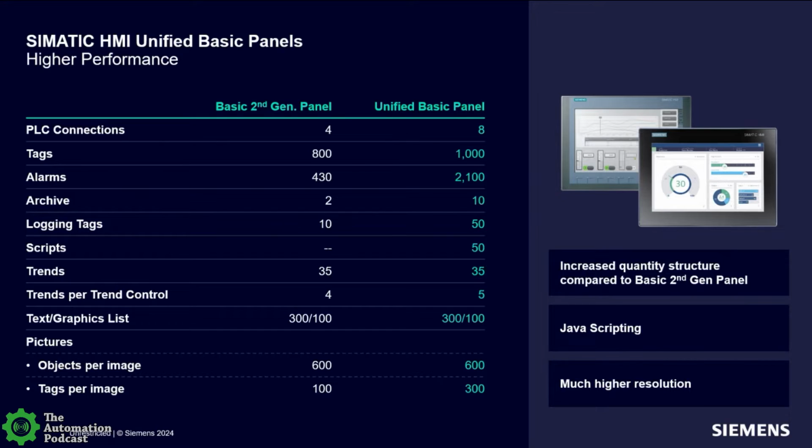But if you start to duplicate that heavily in your project, we like to say use a faceplate, which is a component where you can make that collection of objects together, and then you call that instance of the faceplate as many times as you need, and you're just mapping the new tag information to these faceplate instances. The power of doing a faceplate over grouped objects everywhere is, if you need to make a modification to that graphical grouping, you can do it in one place with the faceplate and then push that update to every use case in the screen or in the project.